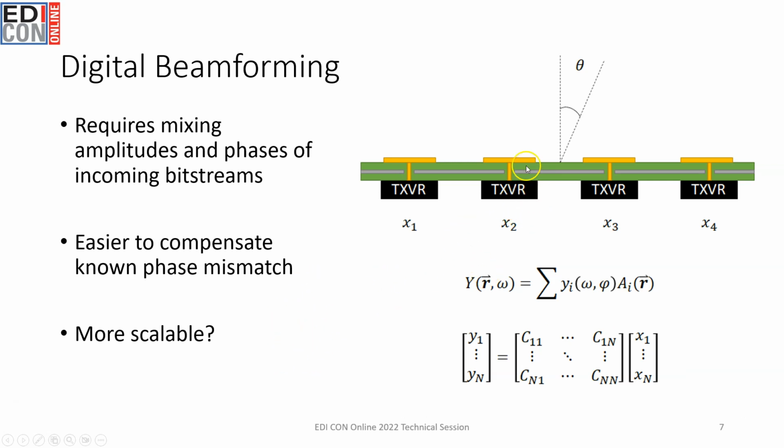But in any case, you still have all of these individual elements. You're going to have individual chips here that then have to route all of these signals into the antenna elements. So you have all of the antenna elements on the same layer, and at some point, as you increase the number of antenna elements, you just don't have room for any of the chips. And so you then have to draw these interconnects as coming from these chips on the back layer or on an internal layer, and then through a via up to the top layer so that you can actually broadcast the beam and do beamforming.